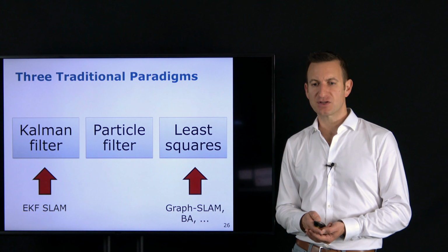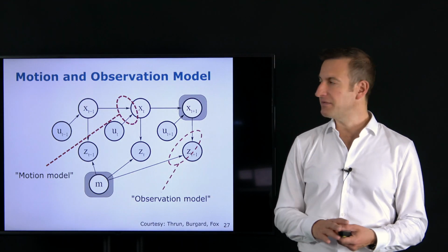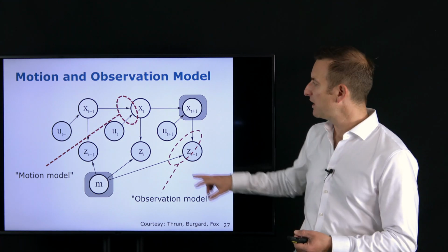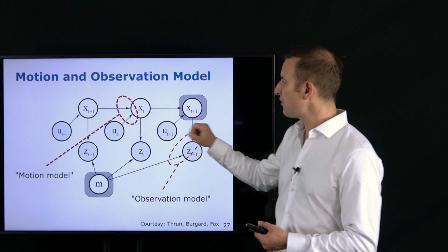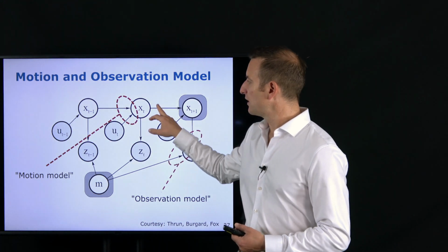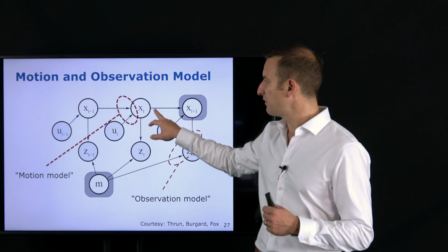If you link that back to our graphical model that I had about the online SLAM problem, then we can actually see that for estimating the probability distribution about my variables, one, the poses, if you look at the local surrounding of that estimate, so what are the variables which impact this variable?